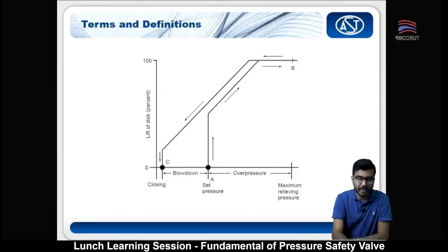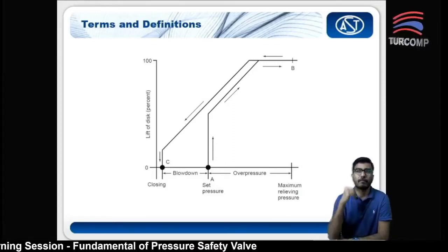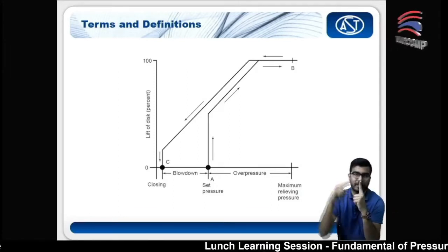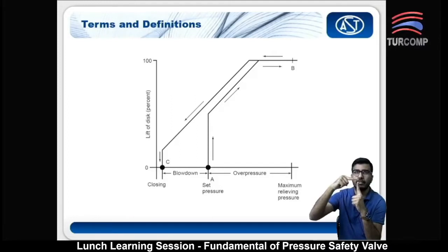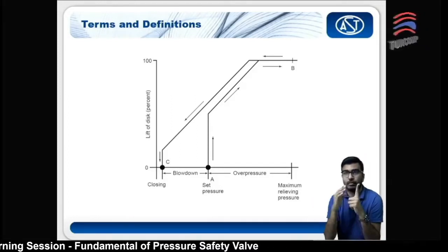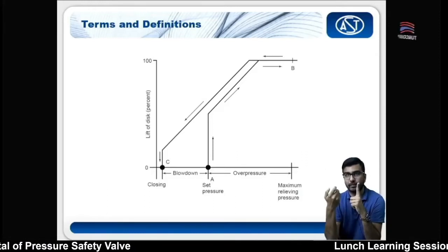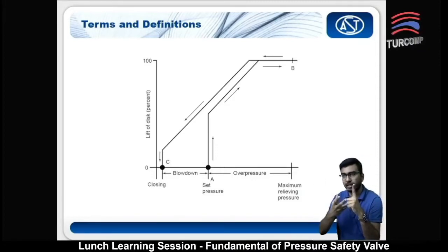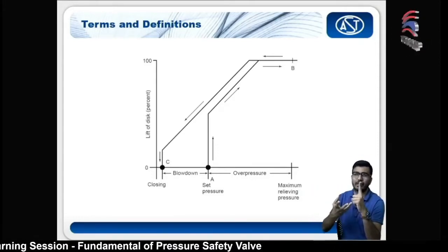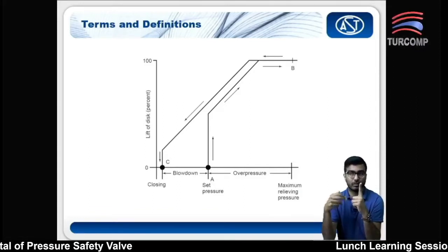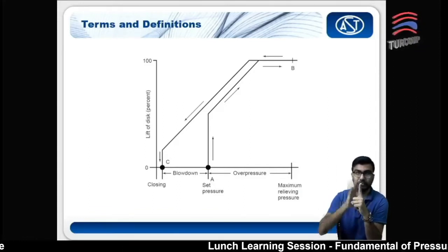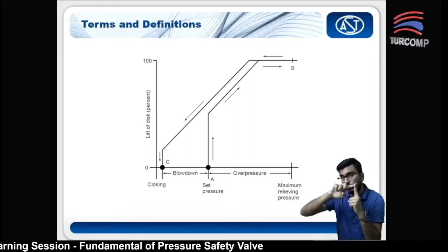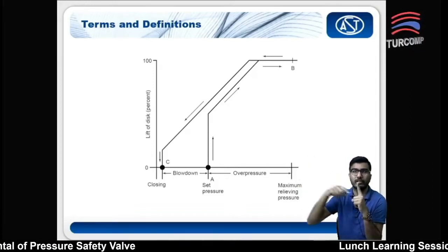Okay, moving on from point A to point B, as you can see, as it goes up, meaning to say your pressure starts to lift, but the highest point of the straight line from bottom to the top is actually somewhere around 50%. So you will lift and then you will still start to relieve. So when it started to relieve, the pressure still escalates more, because sometimes when you open you will have other contaminants coming in. Some of the common things that will come in is actually your oxygen, so you will make the pressure spike more. So that's why when the straight line goes to your point B, you will see the pressure will rise more. So it is actually relieving.